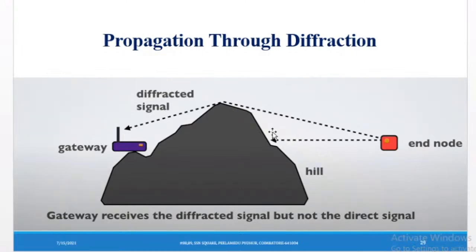So it is reflected back, or penetrated through that chimney, and I'm getting the signal, but it is a weaker signal. So depending upon the environment and where we are going to deploy, we have to select the antenna, which gain antenna I'm going to use, and which altitude I'm going to place it at. It's very, very important as per deployment cases.